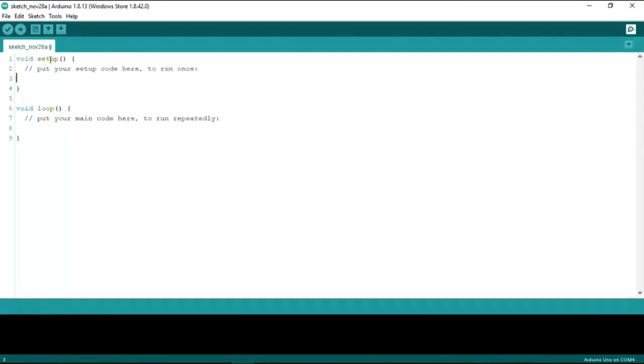For uploading the code, when you finish writing the code, you press this, and it will compile first and then upload. The error you should see here: if it cannot compile, you will see a compile error. If the problem is with the upload, it will show compile complete and then cannot upload to the board. You need to read the error.